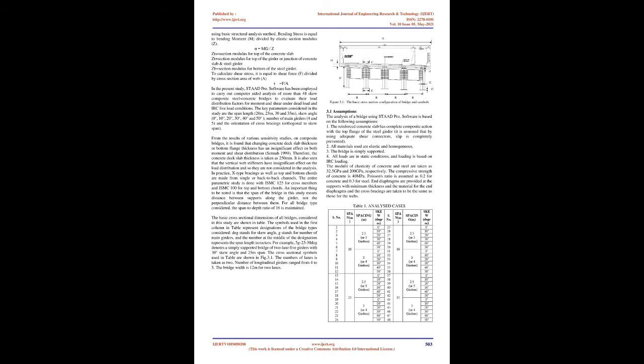The analysis provides useful information about the variation of support reactions with respect to change in skew. Negative reactions were observed with increase in the span and skew angles. It was found that in skew T-beam bridges, the high positive and negative reactions develop close to each other.